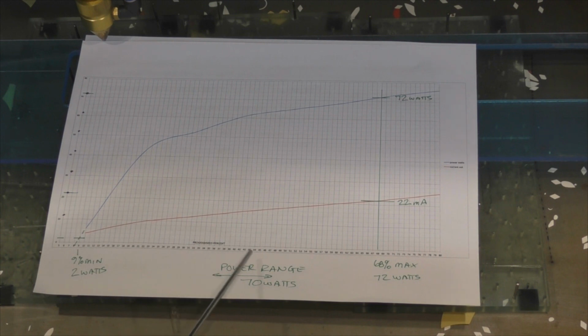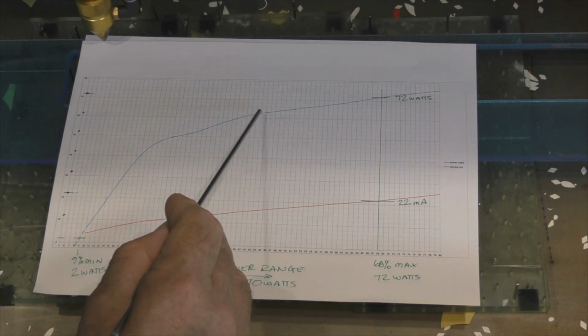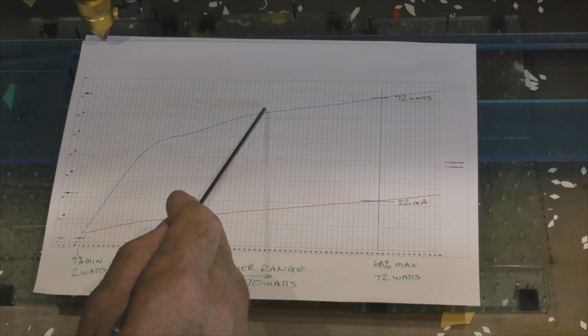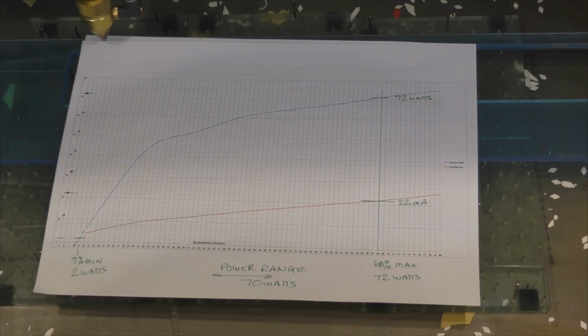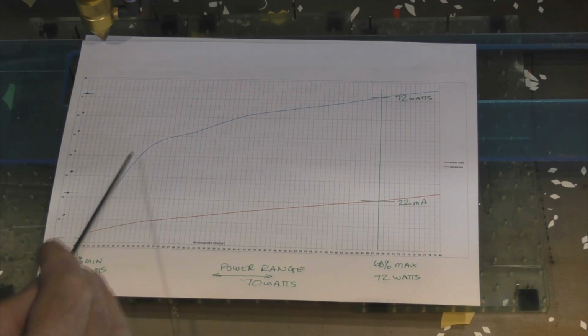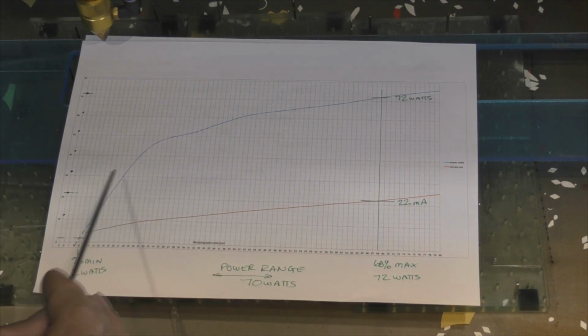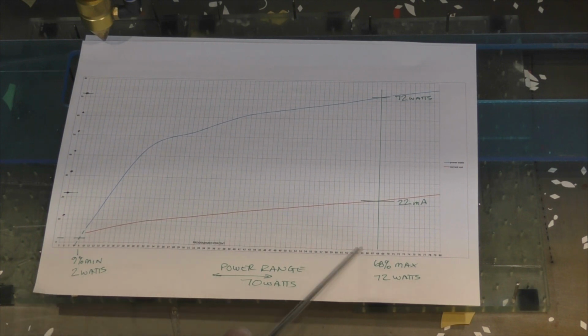But of course, 50% power is not 50% power. 50% power is nearly sort of 70 or 85% of the power. So there is this serious problem that we've got to deal with, where if we want good 3D engraving, we really are trying to somehow linearize this relationship between pixels and power. It seems an impossible task, but for our test purposes, we can do it.